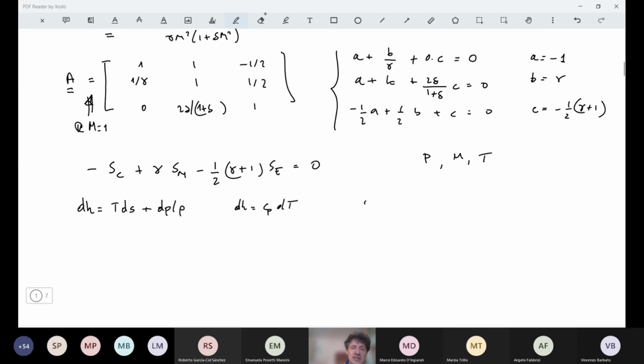So we can say that ds over R will be equal to, dividing by RT, where Cp is gamma R over gamma minus 1. And so we see that here, instead of dH, we have gamma over gamma minus 1, and RT will be a denominator, and so it will be gamma over gamma minus 1 dT over T. Then the second term we bring onto the left-hand side of this equation. That means the right-hand side here is dP over rho RT, which is exactly P.